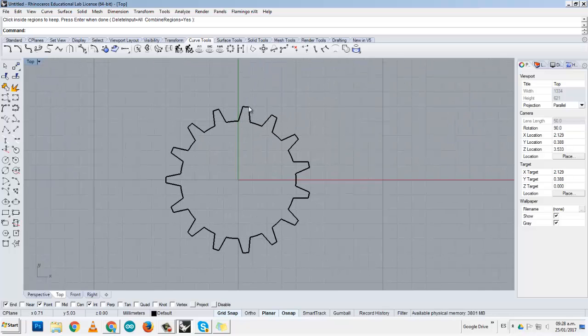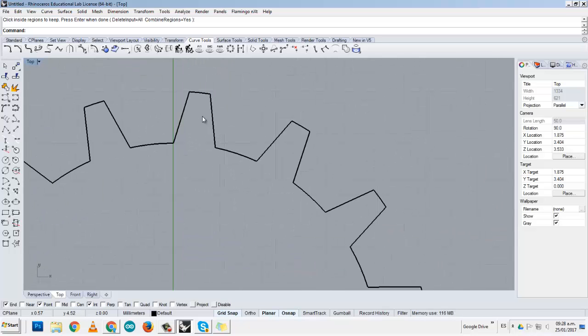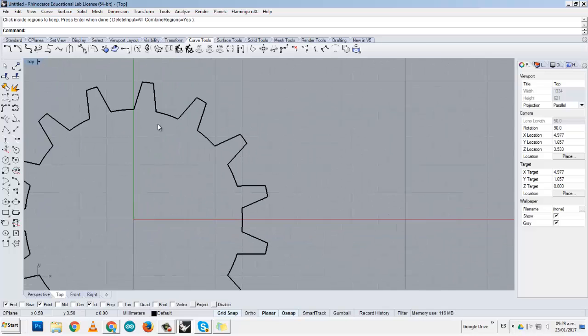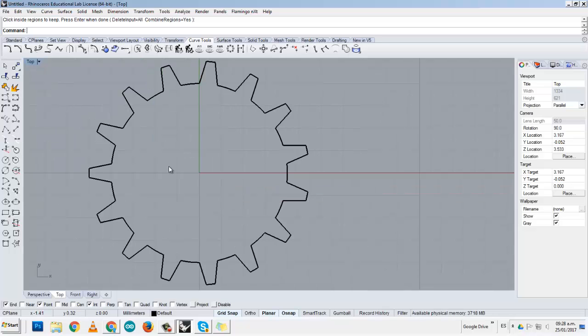I make sure that I have the addendum circle, which is the outer circle of the gear, and I have the inner circle of the gear, or the dedendum circle. Now this configuration here is the one that we can actually calculate using equations. What is the thickness of the gear, and what is the pitch, the imaginary line. So that is extremely important.